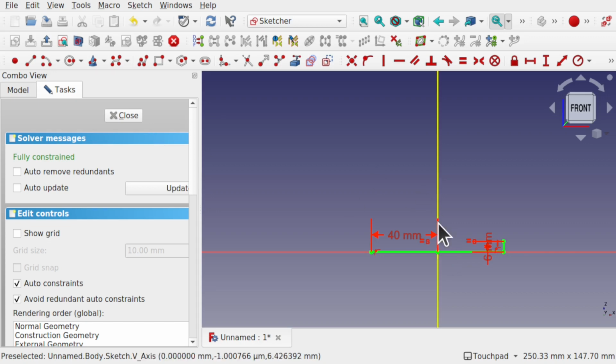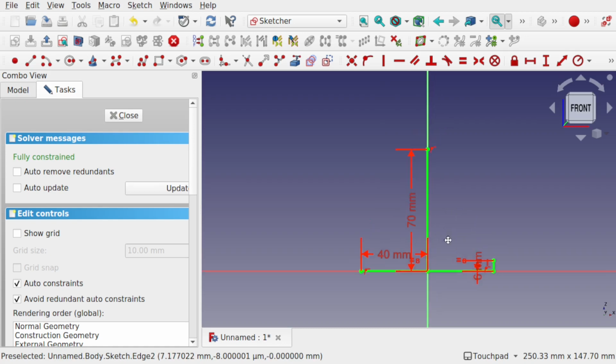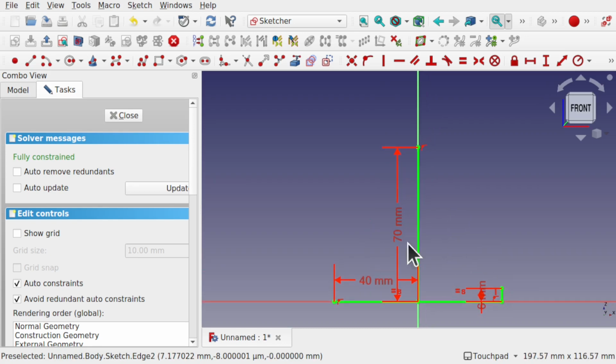And now we want the height of our loft. So I'm going to use some geometry for that as well. So I'm going to place a line in here and set the length of that. So I'm just roughing out the object. That means I know I'm at the right scale down here. Let's set some height quickly. So about 70 millimeters. And it also gives me an idea of what the object's going to look like in a very rudimentary form. I'm going to have a circle here.